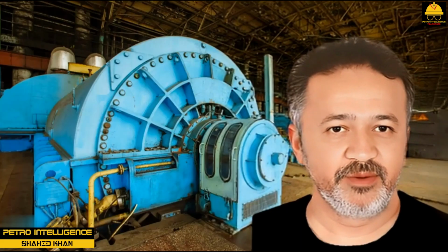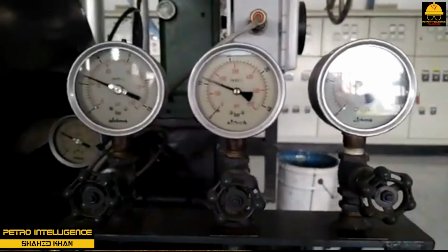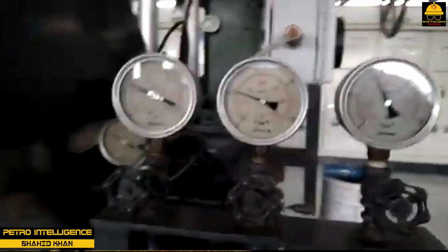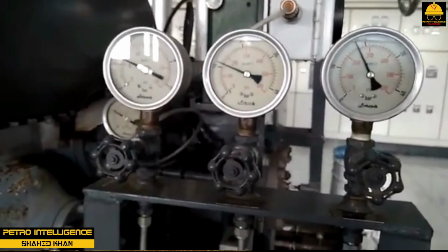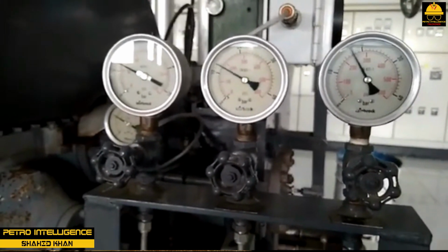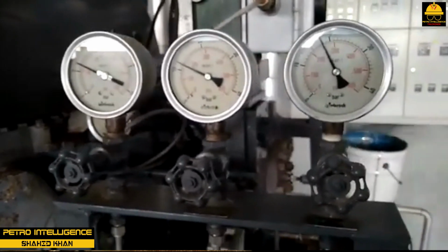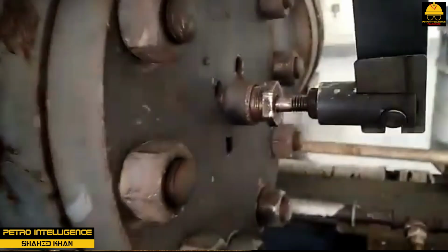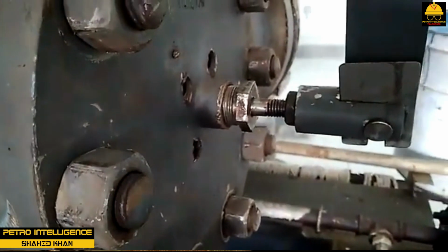Steam turbine problems. Steam turbines are susceptible to 2 types of problems: vibration and hunting. Vibration sensing equipment is used to monitor turbine performance. Probes are used by process technicians to check inboard and outboard radial and thrust bearings. Excessive vibration could indicate failing bearings or internal problems. There are 2 types of vibration: radial vibration and axial movement.